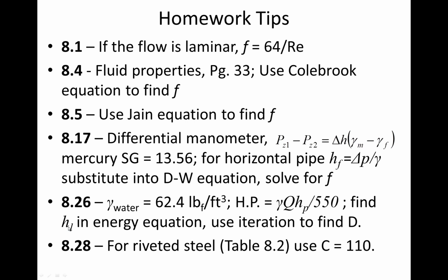Since you know how much pump head is being added and you know all the other terms in the energy equation, you can use the iteration approach that was demonstrated in the last part of the last lecture and in class today, how to find D. That approach of starting with a guess F value and finding out what diameter that would give you and then correcting. We're going to go through that example again in this lecture, so that you'll apply that approach to solve the rest of problem 8.26 once you have calculated the head loss.